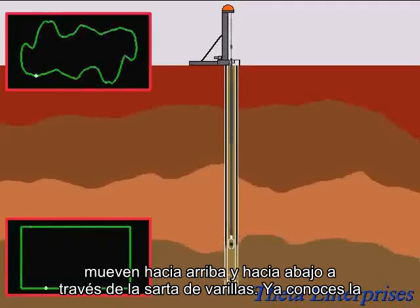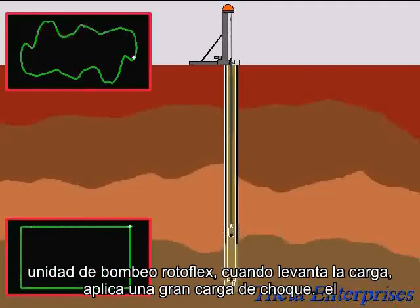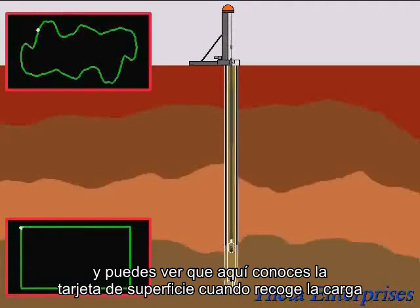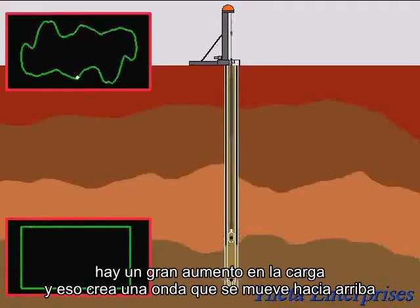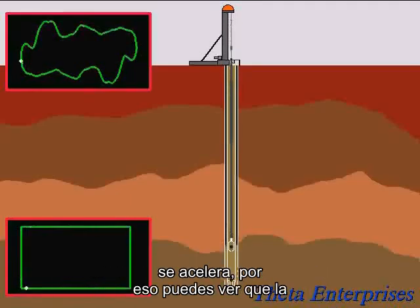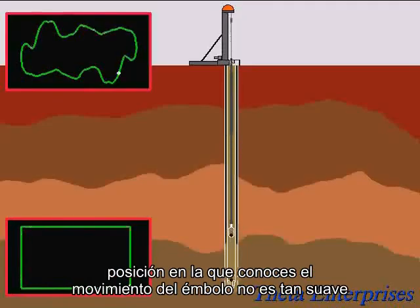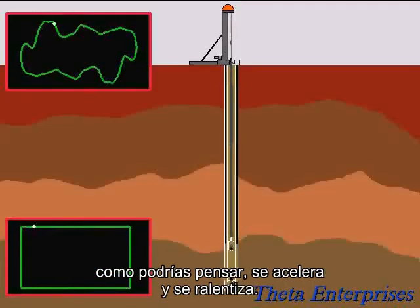When the Rotaflex pumping unit picks up the load, it puts a big shock loading into the system, and you can see that here in the surface card: there is a big increase in load. That creates a wave that moves up and down through the rod string, and as that wave reaches the plunger, it makes the plunger either slow down or speed up. That's why the movement of the plunger is not as smooth as you might think. It speeds up and slows down.